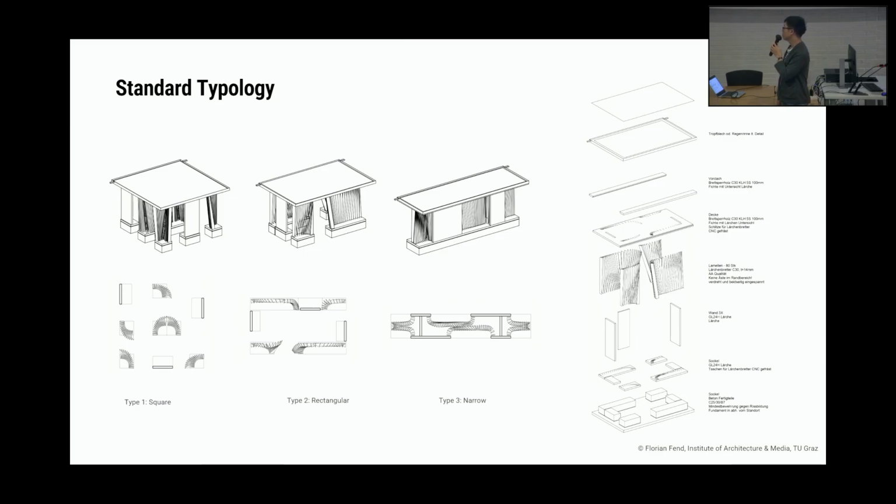And so there are 3 typologies which are built according to the functionality of each of these pavilions, but also according to their snow and wind loads. The last one, for example, which we call the bus stop typology, was critical for where there were really high snow loads and high wind loads, and so we had to build in much more additional stiffening elements, which are these vertical panels to help stabilize the structure. These vertical panels are not only there for showing information about the timber industry and the hiking trails, but are also used as horizontal stability measures.